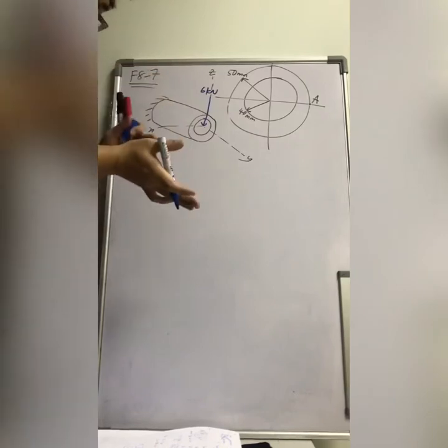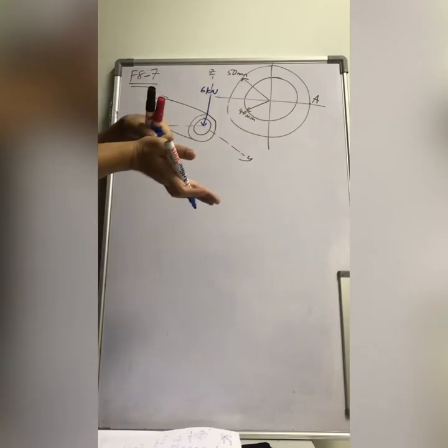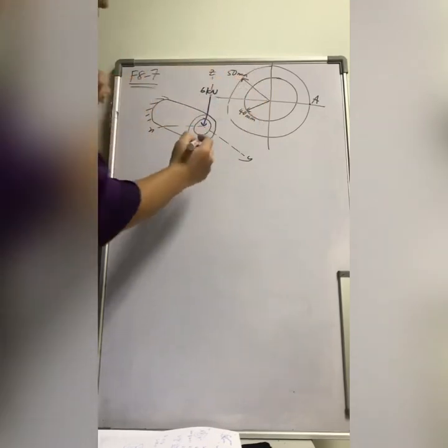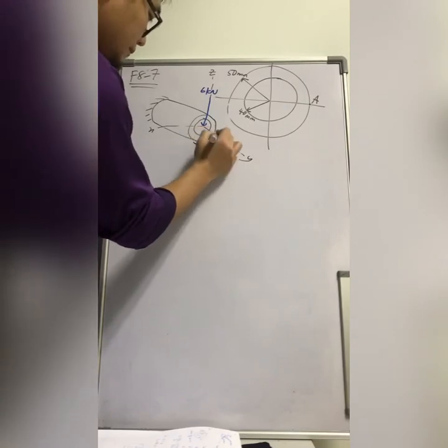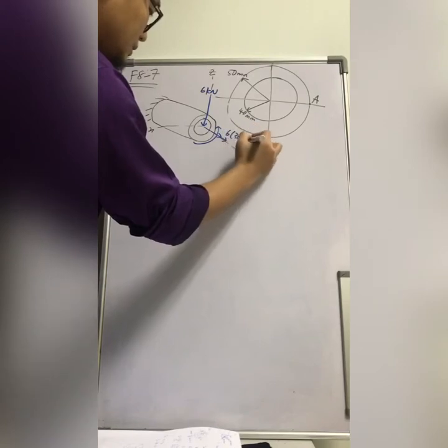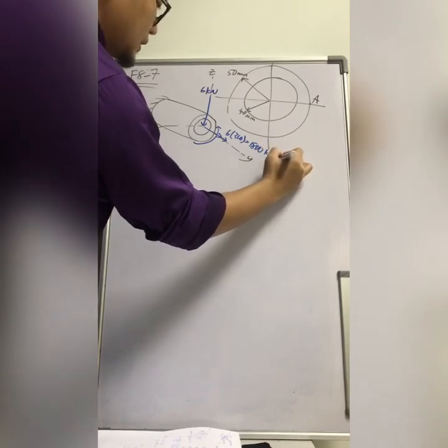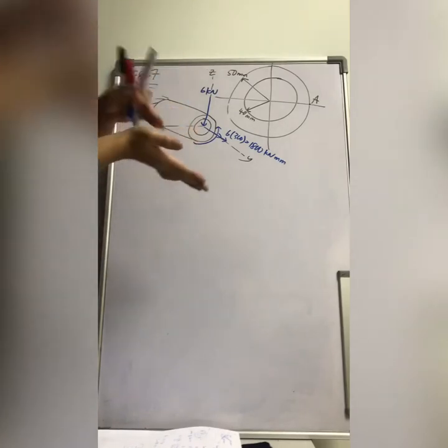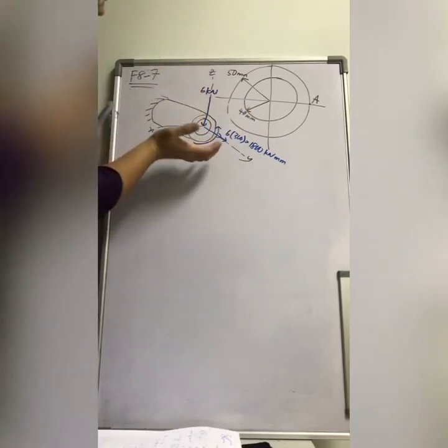Then this 6 kN load, if you take this arm, 300 millimeter, of course this is 300 as well, this 300 millimeter will cause the torsion. So you have this torsional T of 6 kN times 300, which is 1800 kN millimeter. So the one which causes torsion, 6 kN times this 300, will cause torsion.